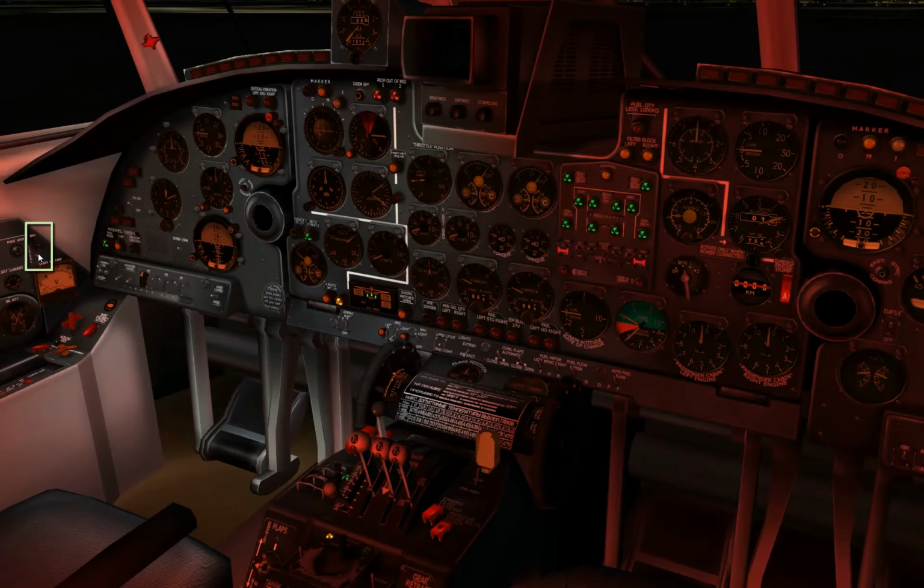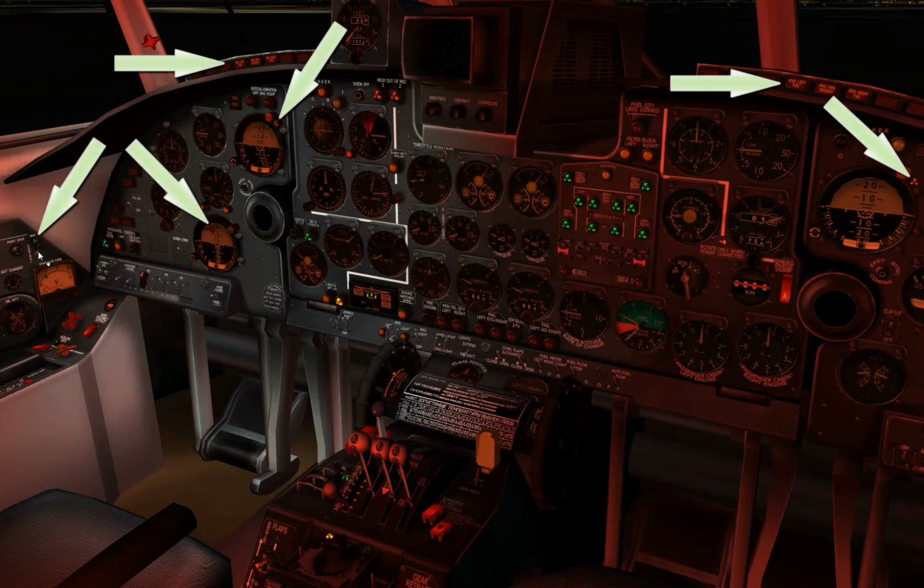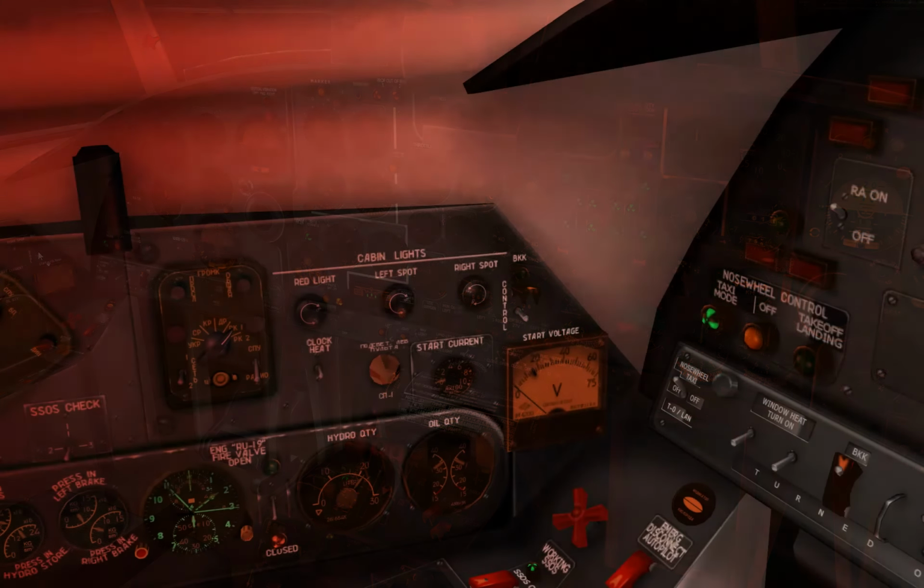This is the roll control unit test switch. When you open the cover and toggle this switch, you will see its green light activate or come on. You will also notice that the artificial horizon or the AI warning lights will light, and the red light next to the AI will also indicate failure mode. Furthermore, the reserve or backup AI failure flag will also appear.